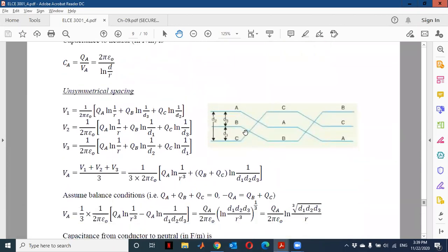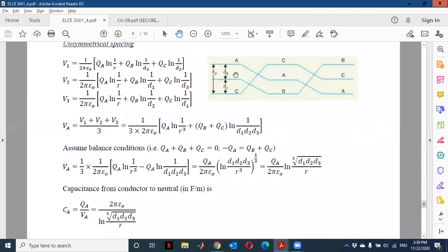If we have unsymmetrical spacing, again, what do we call this method of exchanging the distance of the conductors in unknown length or space? What do we call it? Who knows? What is this method called? Transposition. Don't forget. What is transposition? Don't forget the definition of transposition and why transposition is important in an unsymmetrical spacing transmission line.